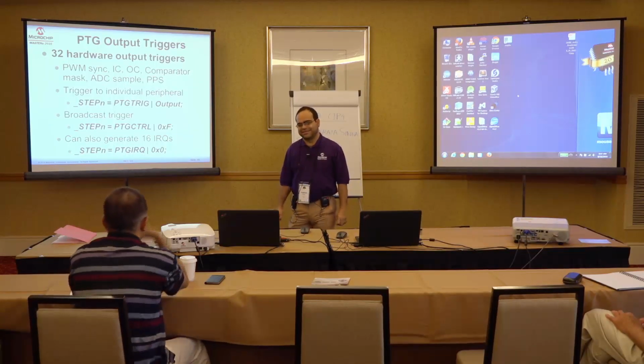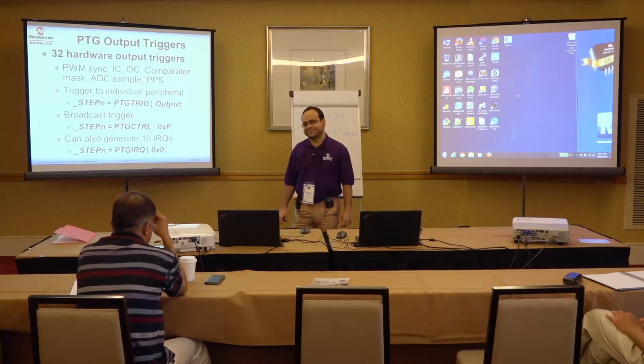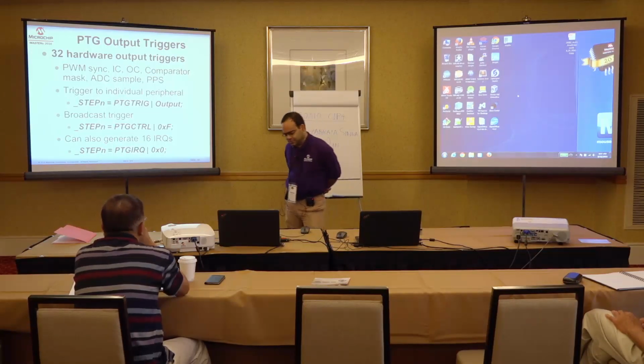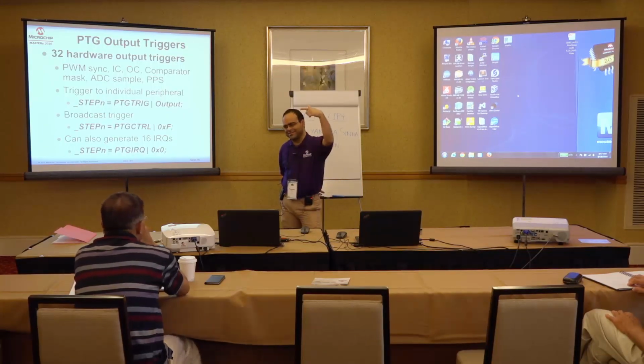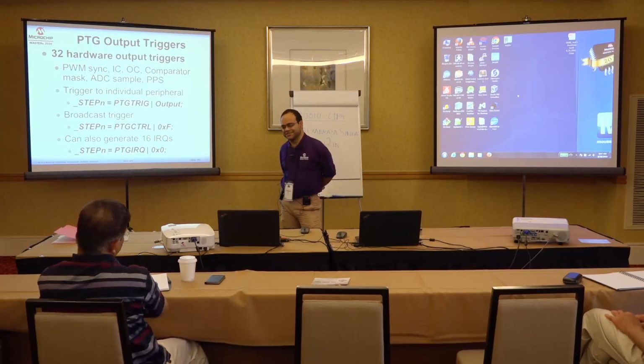Does it have its own watchdog timer? Yes. Is it possible to reduce that? Yeah, watchdog timer, of course. And will it reset the whole module, or will it allow you to continue to the next step? Watchdog timer, when it times out, will stop execution. I need to check on that, whether it goes back to step 0 or whether it continues from that step when you restart it. That way you can overcome this problem, absolutely.